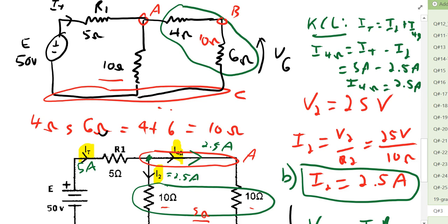Now sometimes you don't need to do the calculations. If you have a bunch of circuits redrawn, you can see that these calculations apply to your redrawn circuits. And so now we had then right here I2 2.5 amps, the current through the 4 ohm then at 2.5 amps. And so as we move back up to our redrawn or more complicated circuits, you will find that we have to move the values we have calculated for the simplified circuits to the larger circuits.